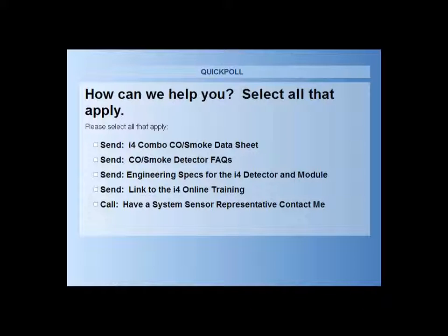Okay. Doug, I know one of your slides talked about the module and the recommendation to put it within 20 feet of the panel. Why is that? Why install the module within 20 feet? That's actually a requirement of our agency listing with UL. Okay, all right. So it has a lot to do with the testing and supervision. Okay, very good.